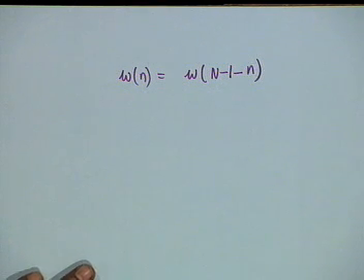If you want linear phase, Hdn is symmetrical. Therefore, whatever function you multiply Hdn by must also be symmetrical, otherwise linear phase shall not be maintained. Now we take a specific case, let us say a low pass design.